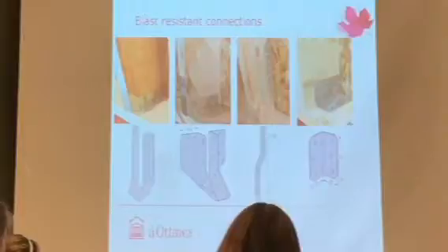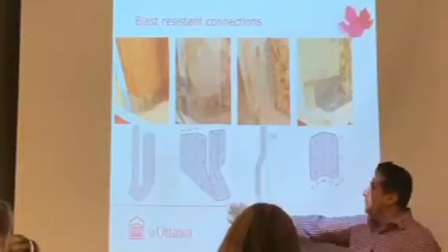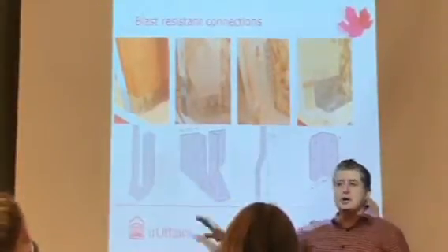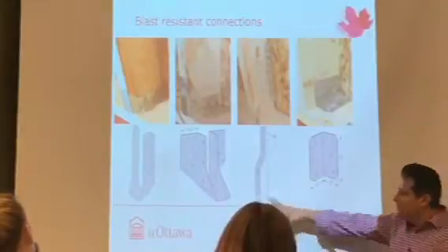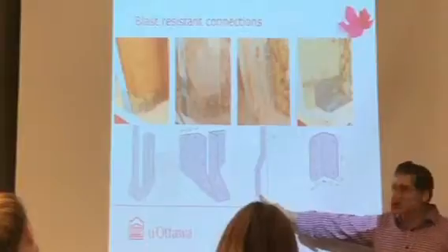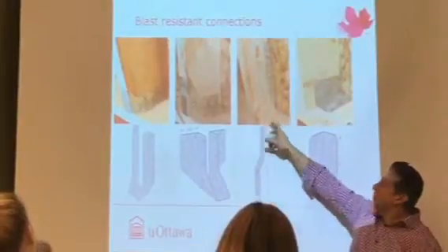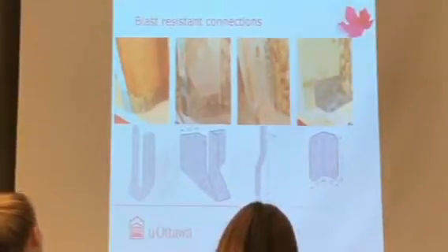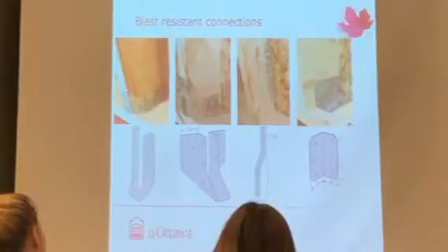The next option up is a sturdier connection. This one was one of my favorite, and it performs the worst. This was one of my favorite because I figured, you know, it's a hurricane strap. It's one where if you have uplift, you grab the rafter on the roof and you bring it down to the stud. You bypass this, right?